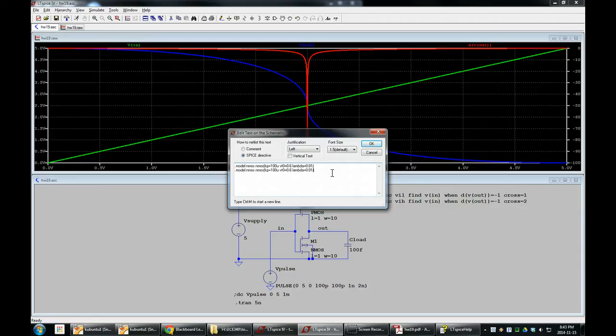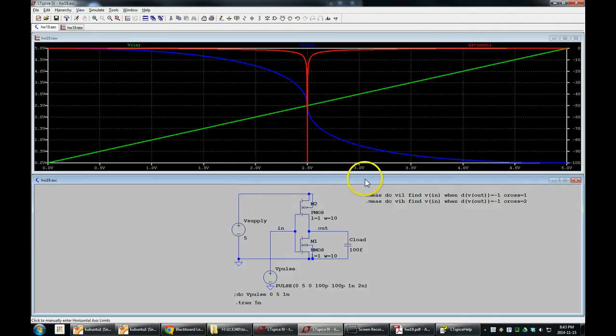Let's just copy paste this. VTO was minus 0.6, but 40 micro. And we have a PMOS transistor. PMOS. All right, so that first simulation really was truly hosed. We'll put it here. So we have our transistor models. These are the ones we want. You get different numbers. All right, let's run a transient simulation.